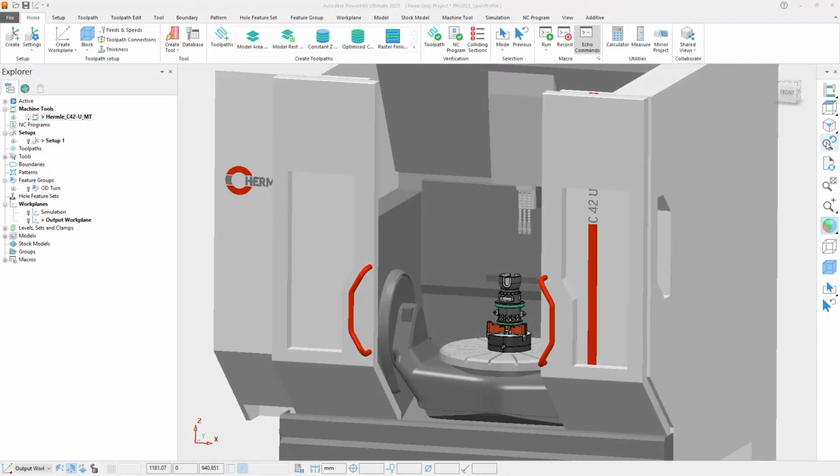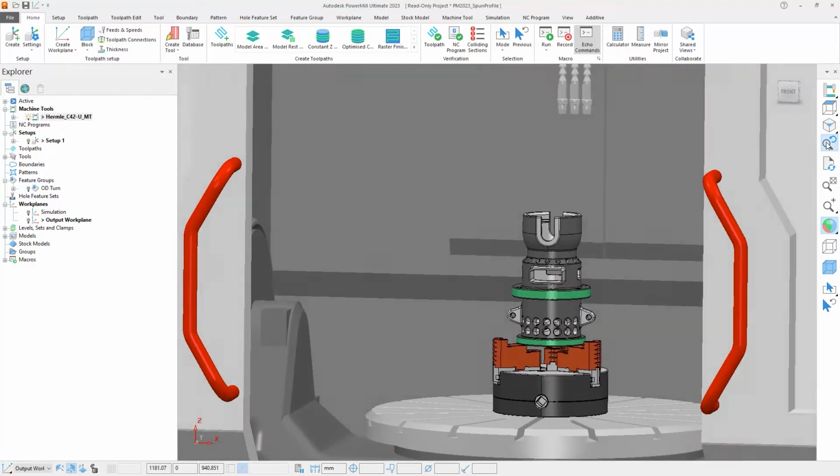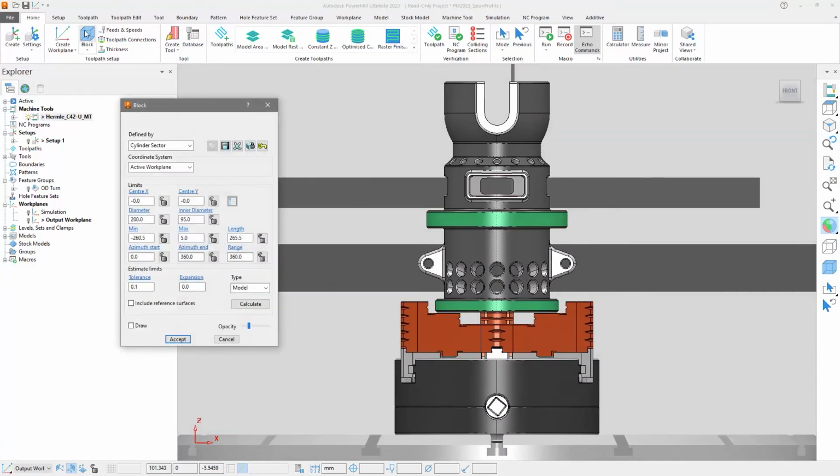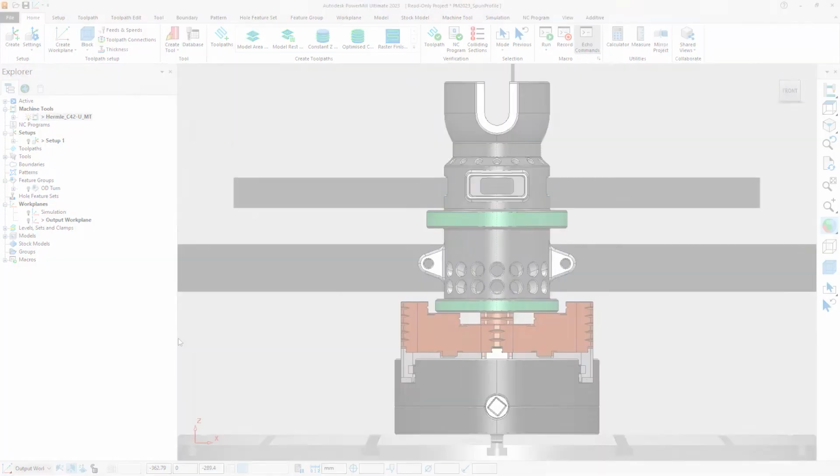Moving on to the second example, the generation of spun profiles, which are primarily for turning feature creation, has been sped up too. In this example, we will be looking at creating the spun profile needed for this mill turn part, which is 260mm long, with an overall outside diameter of approximately 180mm and an inside diameter of 95mm, with the stock material oversized to fit the whole component.